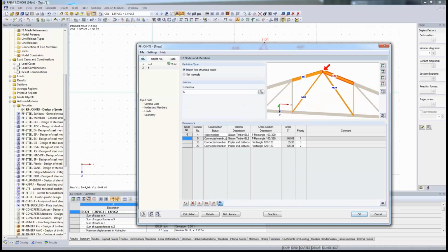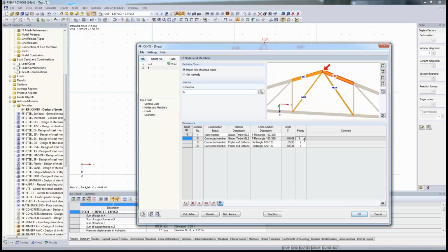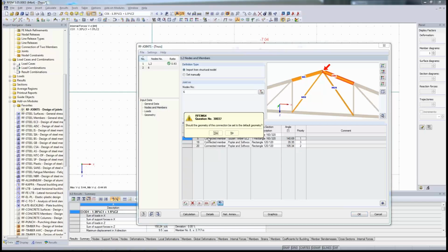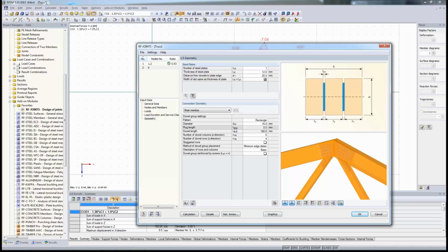And if you change this priority of the attached upper chord to, let's say, 3, you see then it's also still nonsense, because now this is the second cutting of the connection, and it's also not sensible. Therefore, always choose, for such a situation on the ridge, main member, upper chord, and the first priority to the next upper chord.